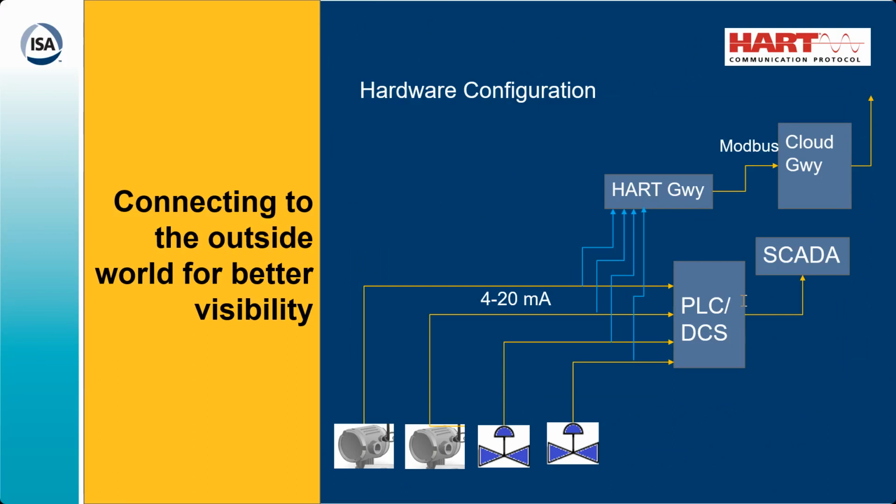But you have to build it with this expert system onto the cloud so that this can be done. But these HART gateways are capable enough to do the basic things like loop calibration or setting the configuration, and all that you can do with this. So maybe the last question we can take.